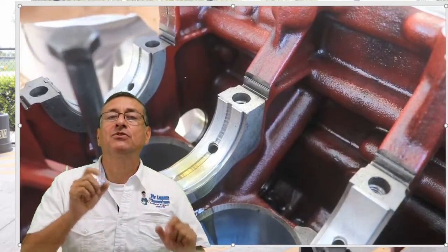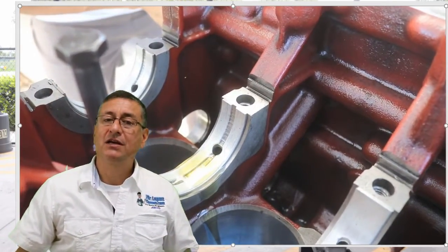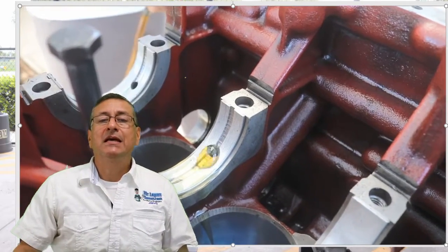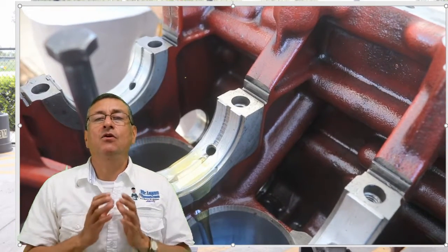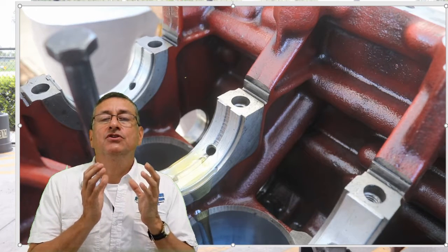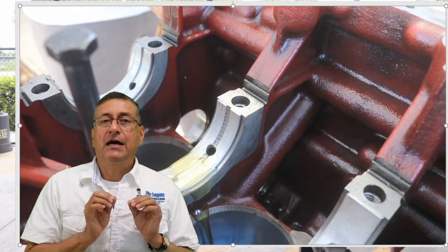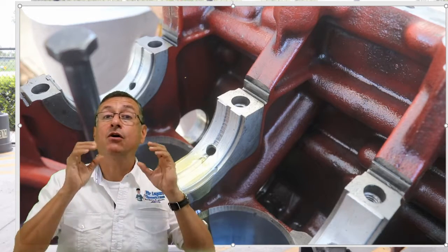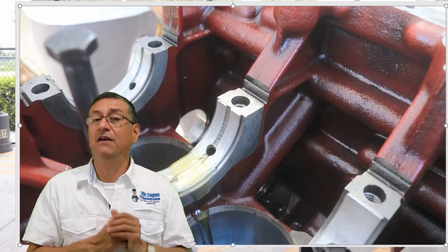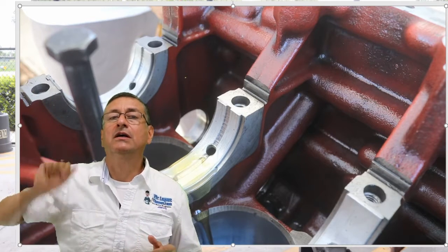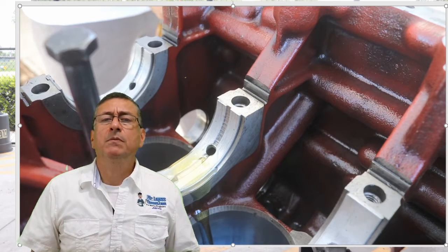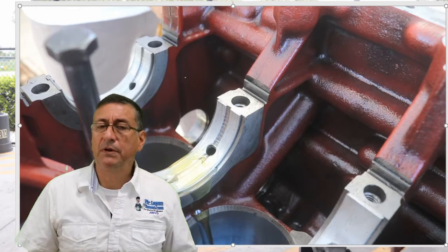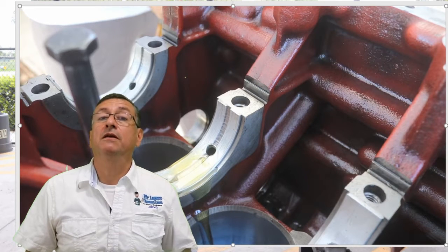And this is the pressure that you read on the oil pressure gauge. For that reason, the quality of the bearings should be appropriate. The quality of the bearings should be perfect, and the tolerance between the bearings and the crankshaft or camshaft should be according to the manufacturer's specification. If not, the oil pressure is not appropriate. Normally people say, no, I am going to replace the oil pump in order to get more pressure. Papi, probably you need to verify your bearings.